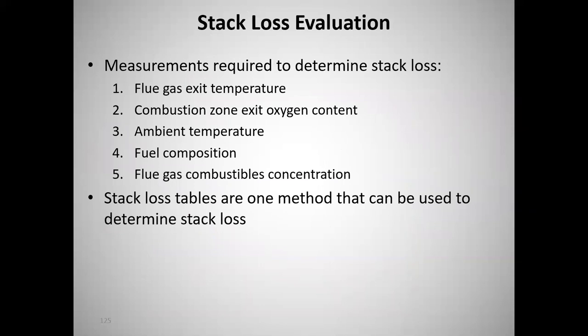Okay, ambient temperature, we need that. We need to know what fuel we're burning, fuel composition, which in most cases is pretty easy. With coals, it's a little more difficult because one load of coal is never identical to the next load of coal, because we're digging this stuff out of the ground. You can say that about natural gas as well, but I think the natural gases are more within a tighter band than sometimes the coals are.